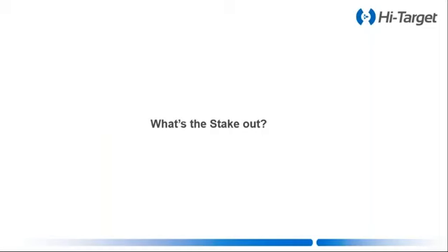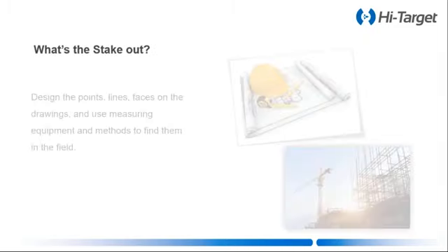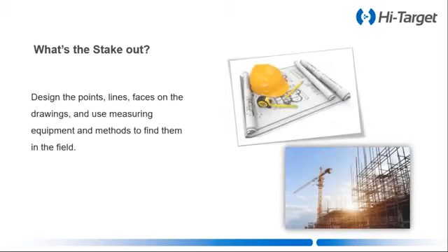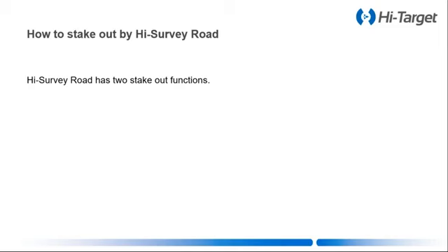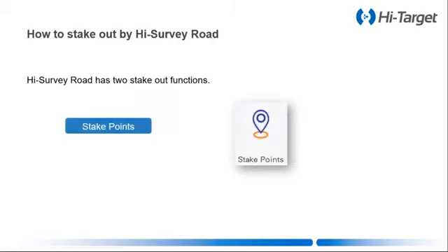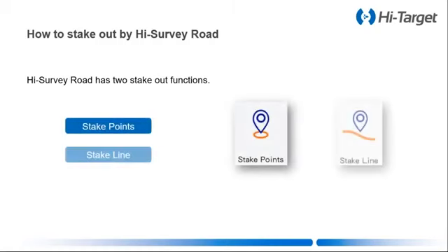Okay, part 3, stakeout. I have a question. What's stakeout? Decide the lines and planes on the drawings and use measuring equipment and methods to find them in the field. HiSurvey Road supports two methods for staking out features. One is stake point and two is stake line.